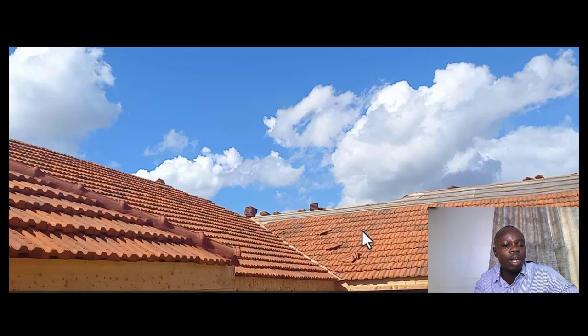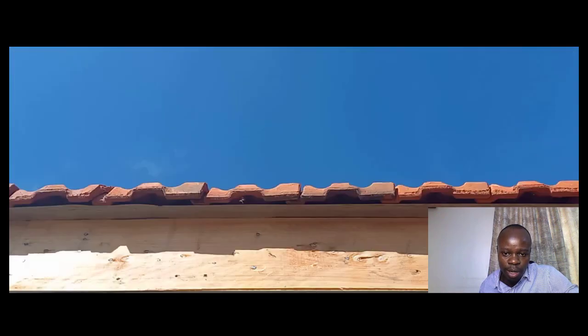Then there are other items. For instance, I've talked about the eaves finishing, like the fascia that I was presenting. The fascia you will do in linear meters, but depending on the size. When it's below 300 millimeters, the rule tells us that we do it in linear meters, then you state the girth. For instance, this is 250.